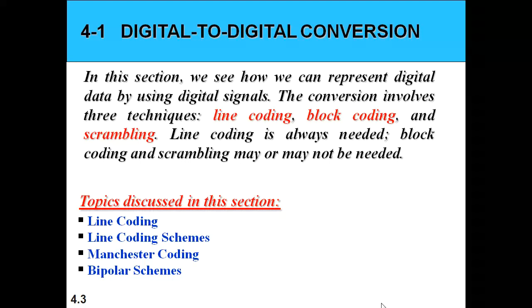In this, we will see how to represent the digital data as digital signals. To convert this digital data into digital signal, we are going to use many conversion techniques like line coding, block coding, and scrambling. But for our syllabus, we have only the line coding technique.